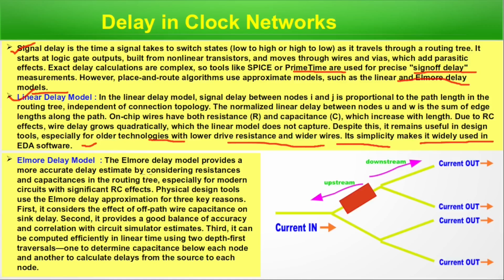with lower drive resistance. And the Elmore delay model, we have already discussed in the interconnect series in the delay episode. The Elmore delay model provides a more accurate delay estimate by considering resistances and capacitances in the routing tree, especially for modern circuits with significant RC effect.